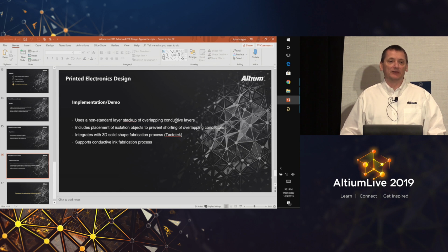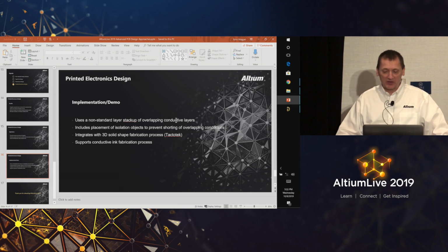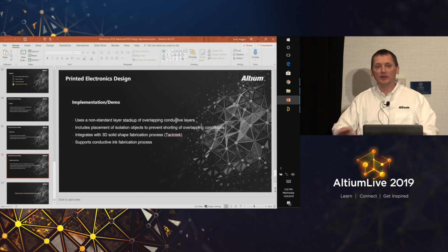You've got to spend a little time with it to line everything up. But there are alignment commands to reference points and things like that. A lot better than it was in 18. And sure, they're hopefully improving that in 20 as well. But you can get things to align based on reference points and alignment and lock them.